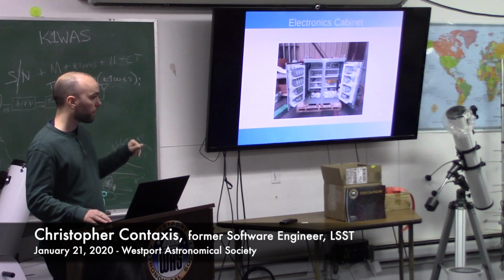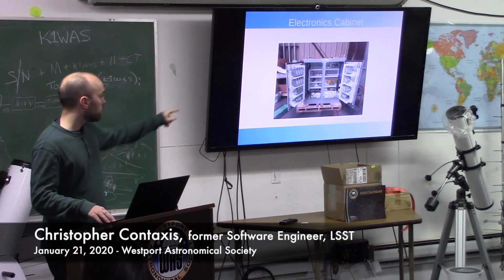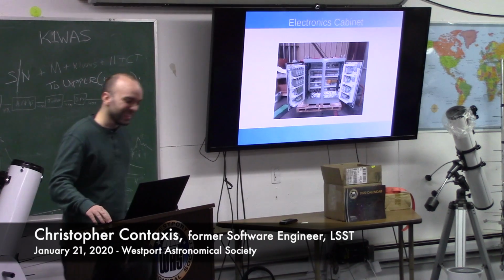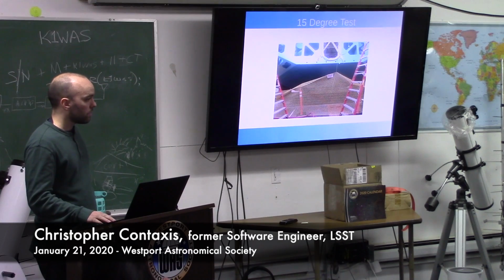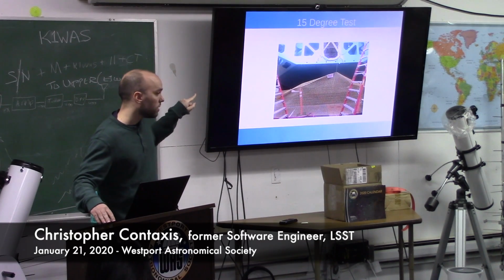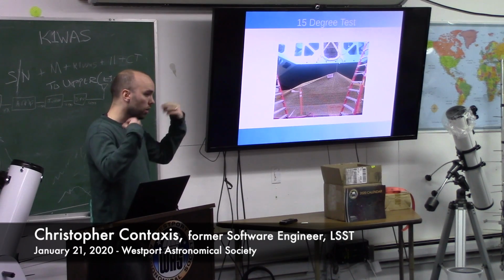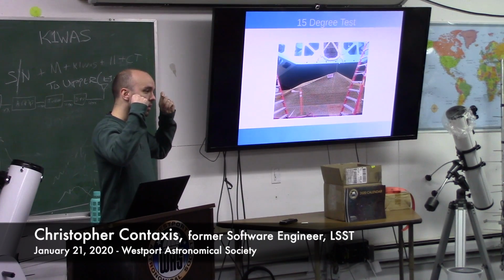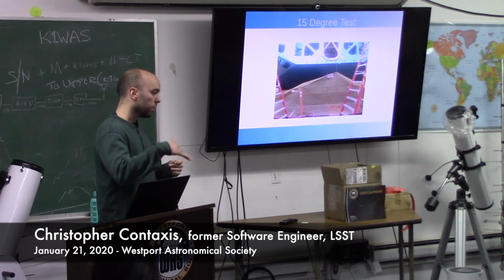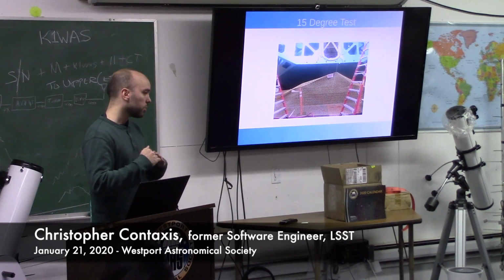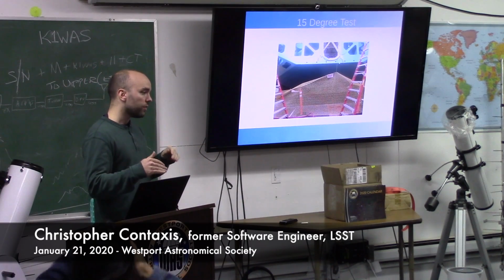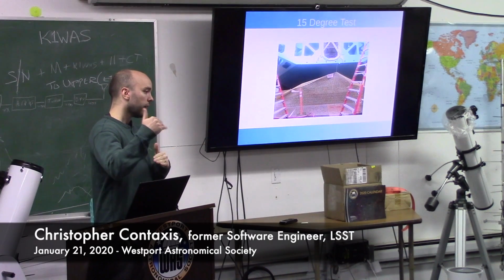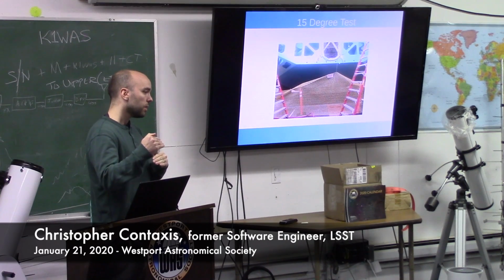Especially since this is going to go on the telescope? Yeah. I mean, this weighs quite a bit, but it's nothing compared to an 18-ton mirror. So you've got some kind of hose going from that thing to take the heat away? Well, you also have coolant going into the mirror cell, because you also have to pull the heat out of all the electronics inside the cell, and then also cool the mirror. So you have heat exchangers and airflow there to try to cool the mirror itself, keeping it as close to the same temperature as the ambient air. Ideally, if you can't keep it there, you always want the temperature lower, because the impact of a slightly hotter glass compared to ambient is much worse for image quality than if it's slightly cooler.